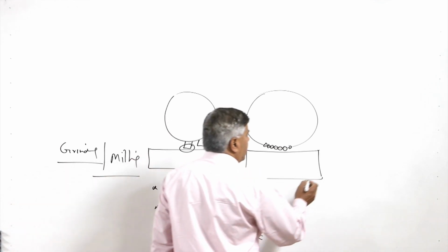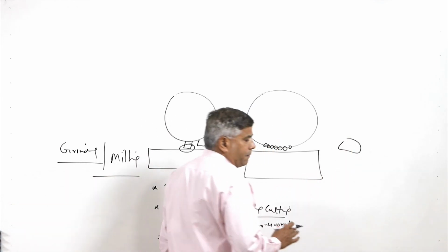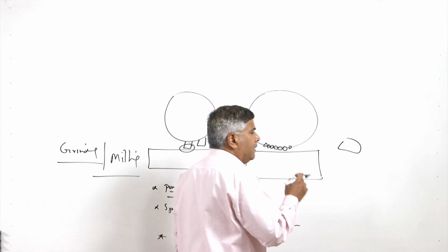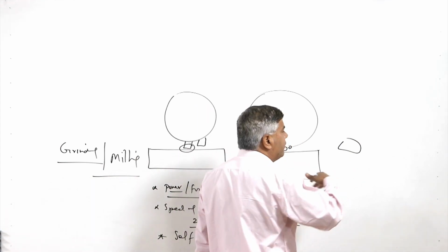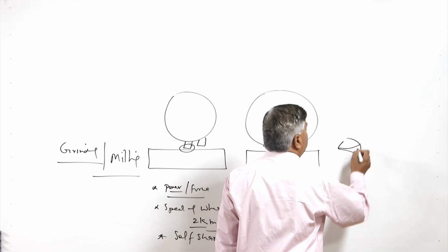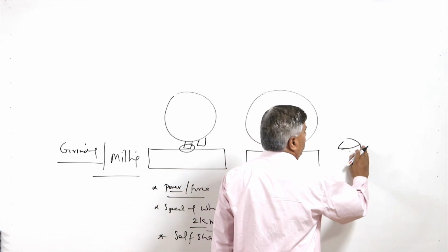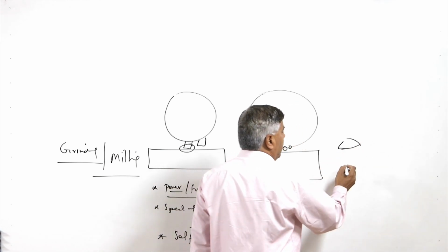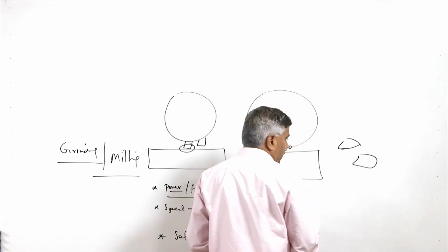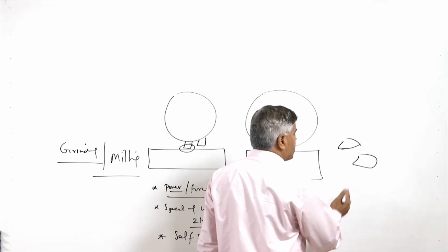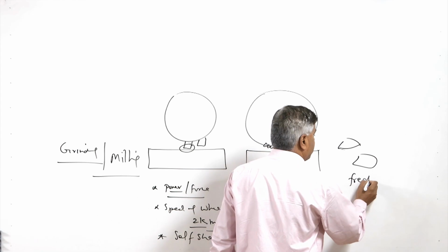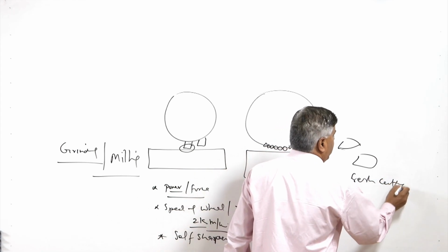But in grinding, after becoming dull or wearing out, the abrasives break or fracture, and the fracture of the abrasives after a certain time of the grinding operation produces fresh cutting edges.